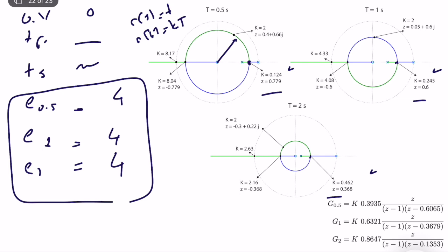So first of all, we know that in terms of gain margin, lower sampling time is better. In terms of overshoot in general, as soon as you are oscillatory, the lower sampling time is better. In terms of peak time, it's better. In terms of settling time, they may be very similar to each other with respect to the actual system. It's generally the case, but we know that the other metrics are also very important.